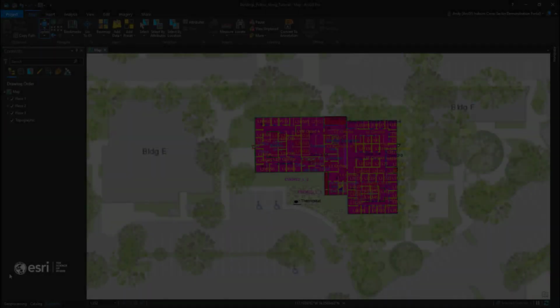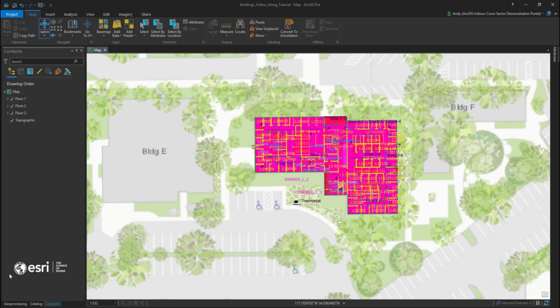Once we have set up our Indoors configuration table and have our ArcGIS Indoors Information Model Geodatabase generated, we can use the Floorplans to Indoors Geoprocessing Tool to import floor plan information for a single floor or multiple floors and buildings. First, go into your geoprocessing pane and search Floorplans to Indoors.